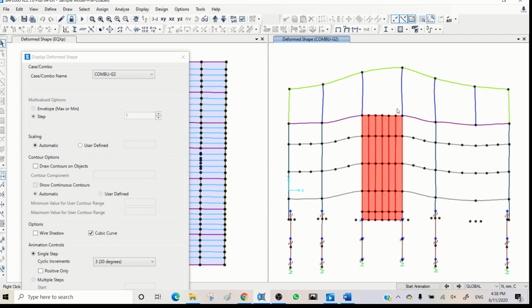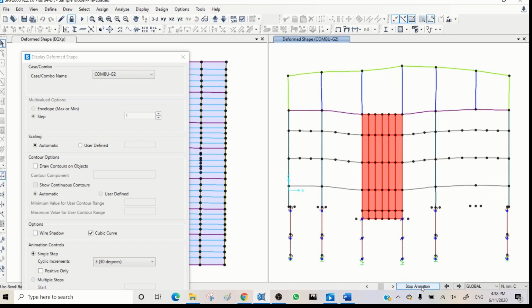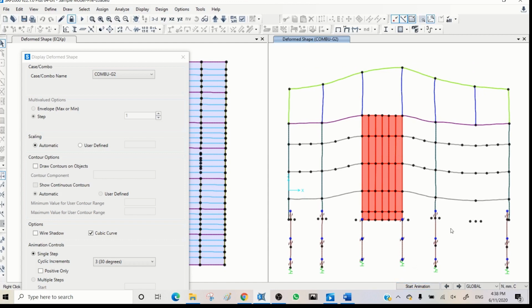Okay, you can see here a big change in displacement, which is not normal. Compatibility of deformation is very important, guys. So here you see the displacement between other piles and these piles is considerable. So you need to make it logically similar. Otherwise, you have some extra forces. The reason could be the springs are not defined properly. There are many reasons. You need to find the reason and fix it up before moving on to design the elements.